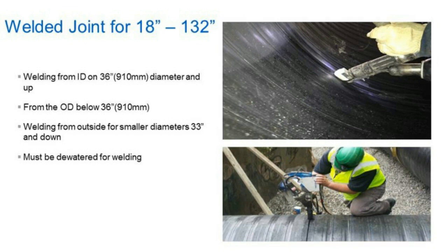So if the welded joint has been planned as the joining method, the OD and the ID, you have to determine how that's going to be performed in the field and what the contractor is going to be responsible to do there. The joint's going to need to be maintained in a dry condition to perform the welding. We always have to have a dry condition and contaminant free. So the welding can be performed by an Uponor technician or other trained extrusion welding technicians that most likely should be approved by the engineer prior to the project construction.